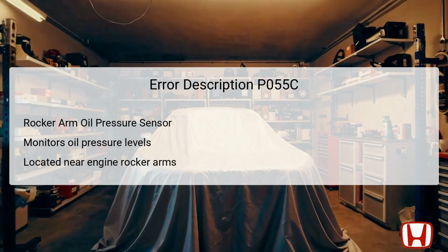When the sensor detects an output voltage that is less than the specified value of 0.18 volts, the PCM registers this abnormal condition, triggering the DTC for further investigation and troubleshooting. This low voltage reading indicates that the system may not be receiving adequate pressure, potentially leading to severe engine complications.